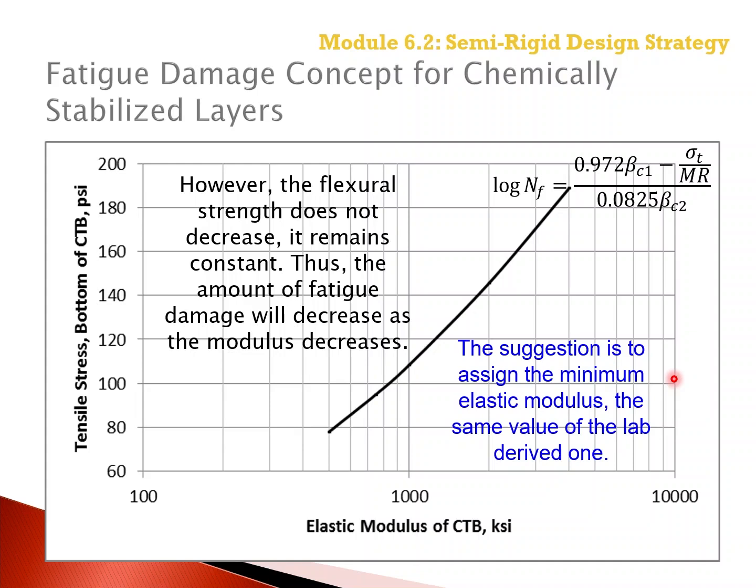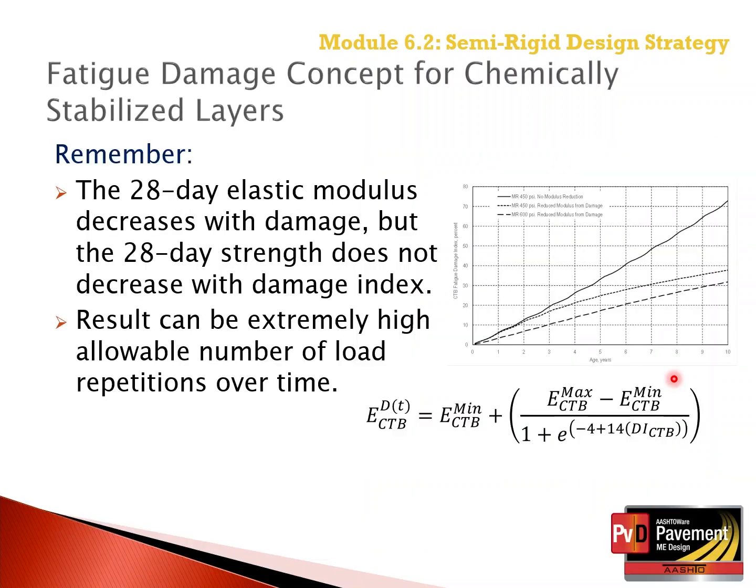Simply set the minimum elastic modulus of the chemically stabilized layer to the 28-day elastic measured modulus in the laboratory, or the 28-day default value.